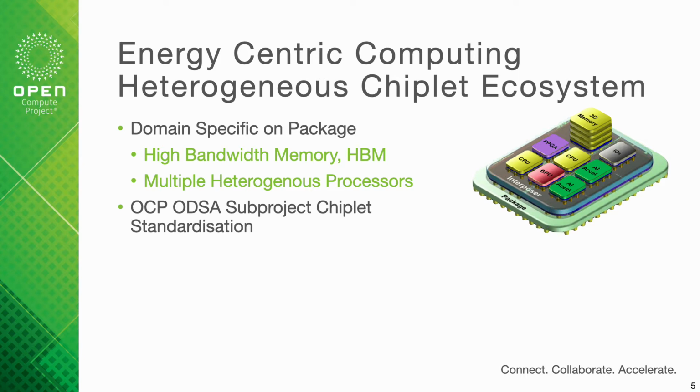High bandwidth memory is probably the most successful integration of chiplets into a package with processors, but everybody's looking towards multiple heterogeneous processors in a similar way to Apple. These are done at the chiplet level, so you can mix and match for your particular application for the most efficient implementation. You'll be hearing from OCP's ODSA shortly. They're focusing on chiplet standardization. Very excellent working group; I thoroughly recommend them.